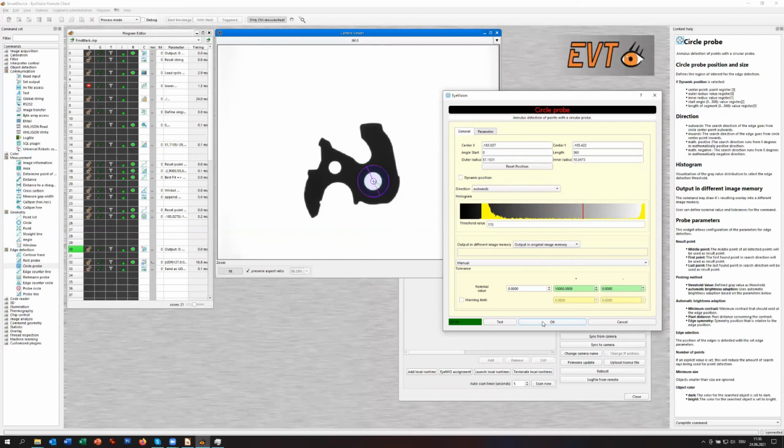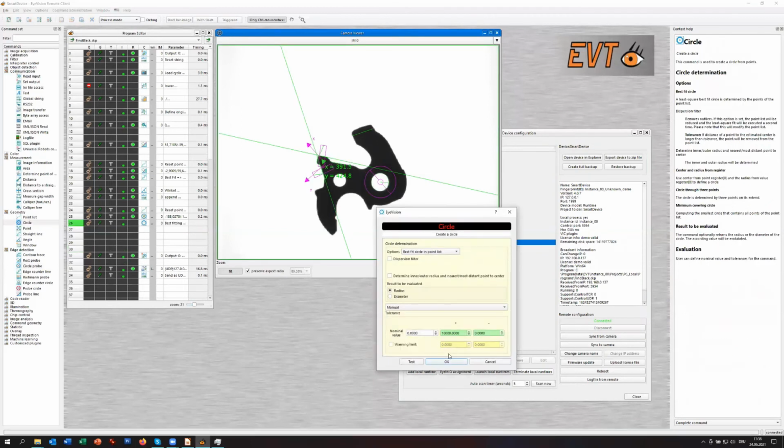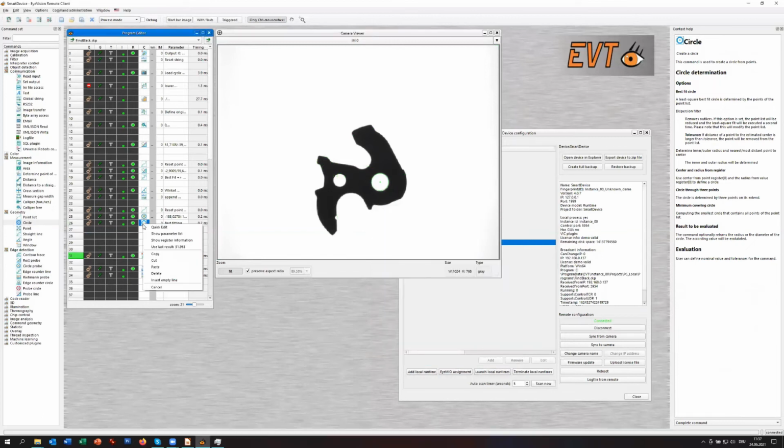And if you finished, as you have to do it with the straight line tool, you can use the best fit circle, which calculates the best fitting circle here inside. And as a result here, we have this diameter. And based on this, we can do some additional resulting operations.